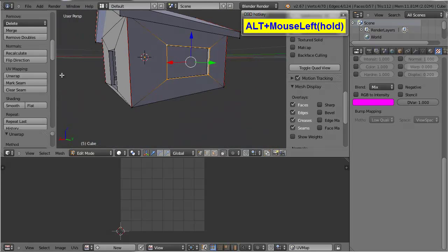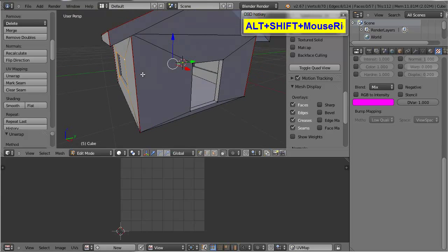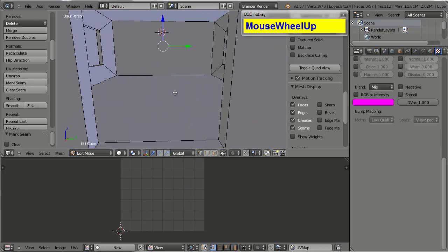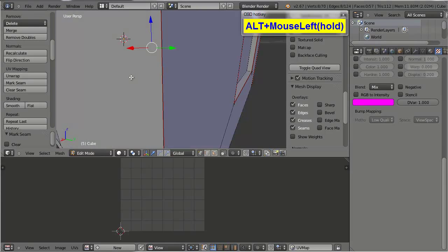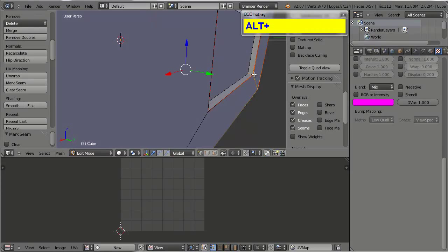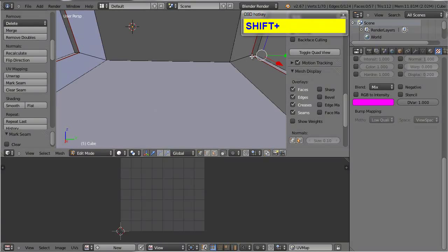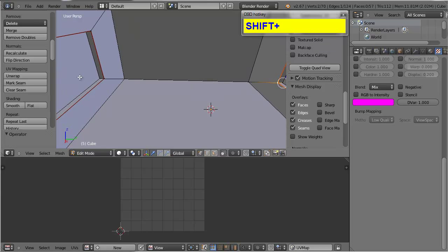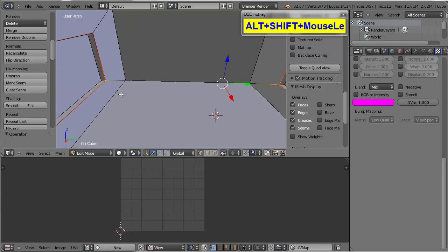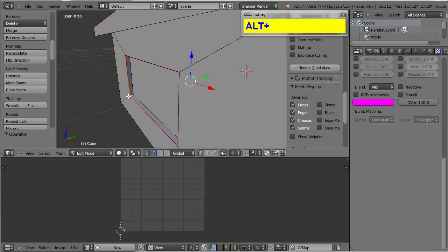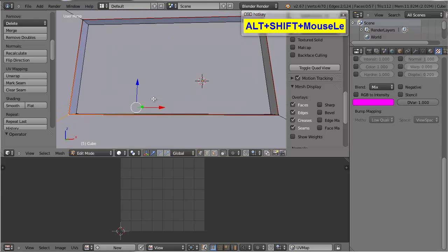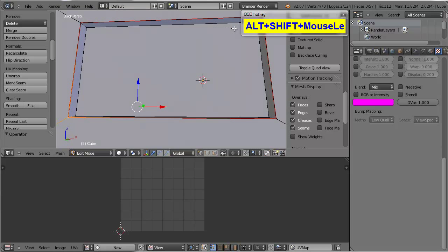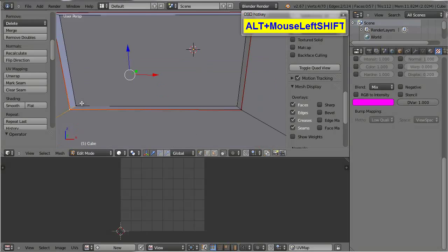So I'm going to select one side and then the other. I'm going to mark seam, and then I'll do the insides as well, and mark seam. And I want to do one corner of the windows. And the reason that I want to do one corner is because when I unwrap this now, it's going to unwrap from this corner all the way around back to that corner.